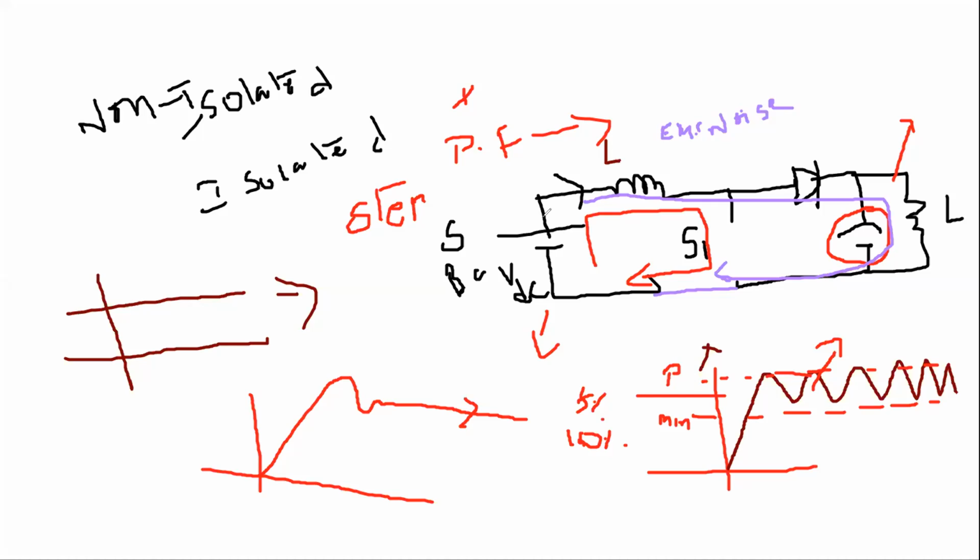In an isolated DC-DC converter topology, we transmit the power from the source to the load side by using a linear or ideal transformer, or mutual inductance. With a linear transformer or ideal transformer, we are sending the power supply from the primary to the secondary side. In high power drive applications or onboard charger applications, most of the companies are focusing on isolated DC-DC converter topologies. But to understand these isolated topologies, note that in all the smart devices we are using, only these non-isolated DC-DC converters are implemented, whether step up or step down.